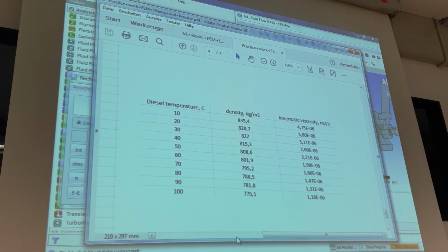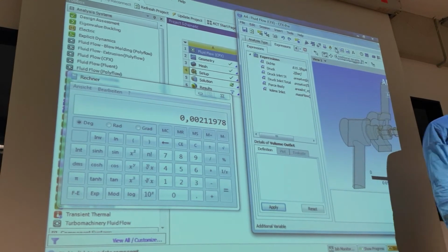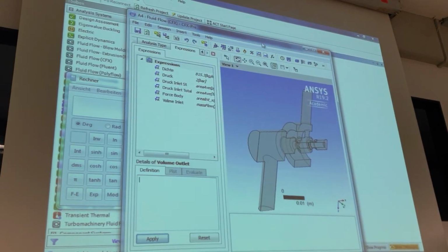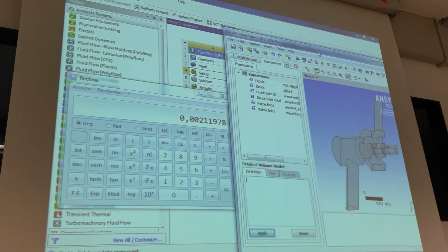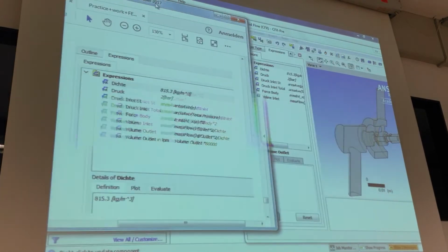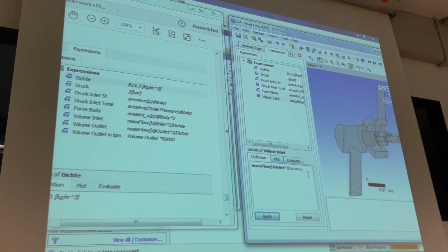And this is the easy way. Other software, Fluent from ANSYS, makes it much more difficult. We need to do it like a C program, a small program in C, and install a compiler. It's much more difficult to define this pressure inlet. So this is the best way, a really easy way in flow simulation. Okay, and what was the last point? Volume inlet, volume outlet. You can copy and paste, of course.